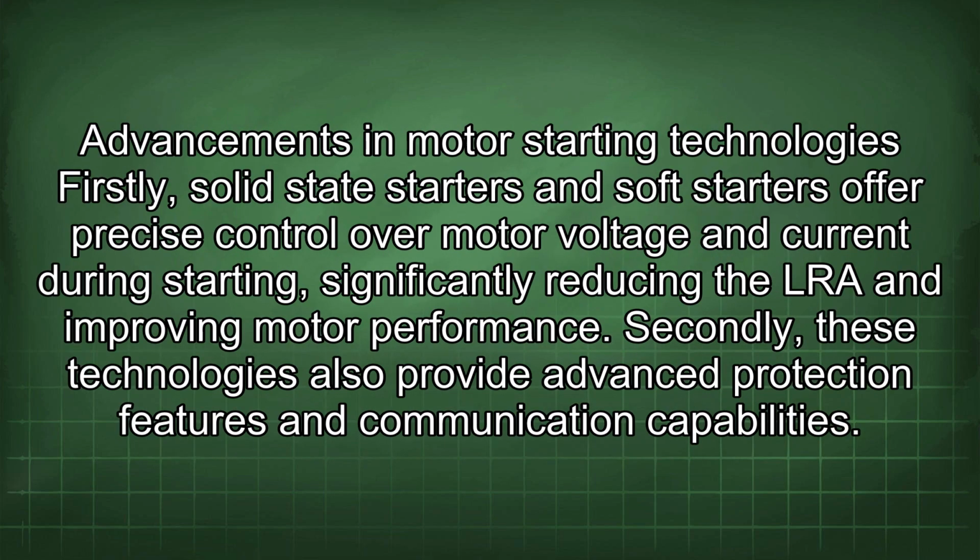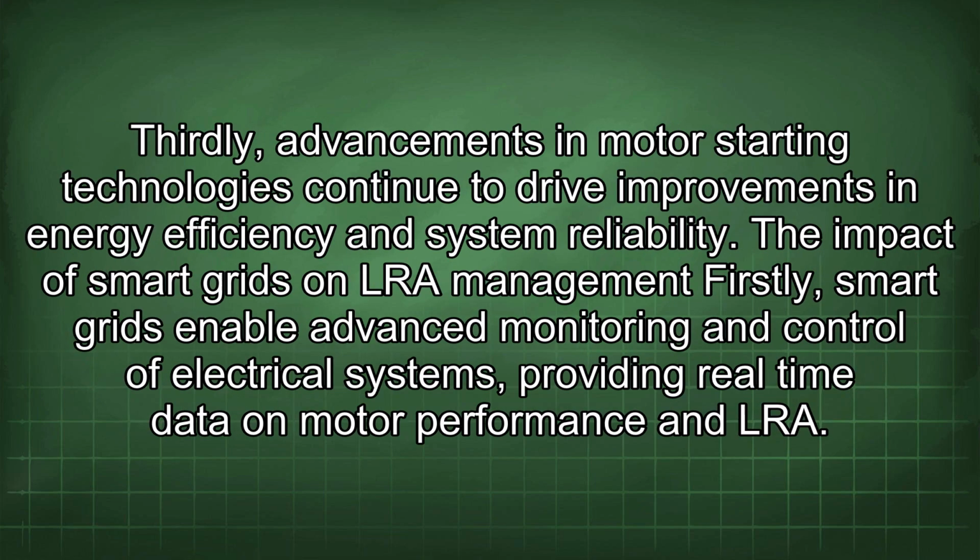Advancements in motor starting technologies. Firstly, solid-state starters and soft starters offer precise control over motor voltage and current during starting, significantly reducing the LRA and improving motor performance. Secondly, these technologies also provide advanced protection features and communication capabilities. Thirdly, advancements in motor starting technologies continue to drive improvements in energy efficiency and system reliability.